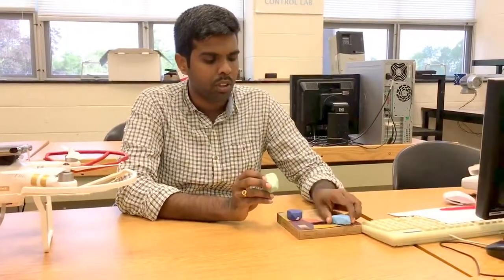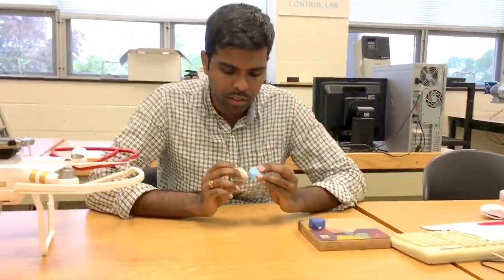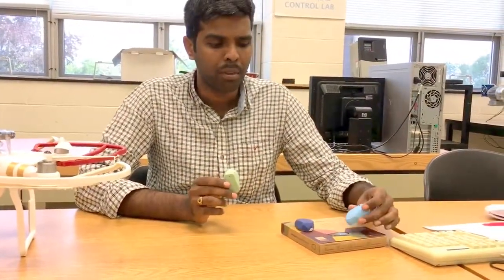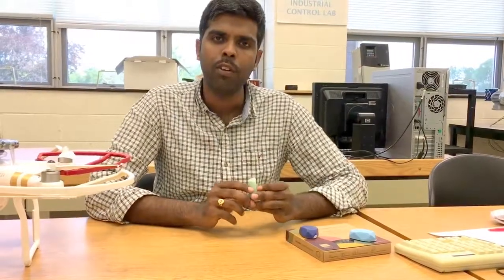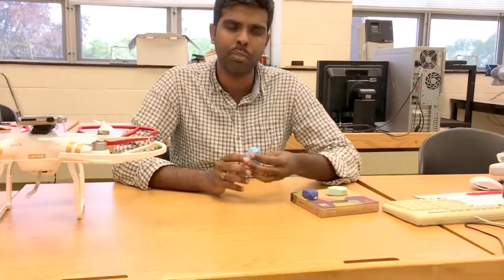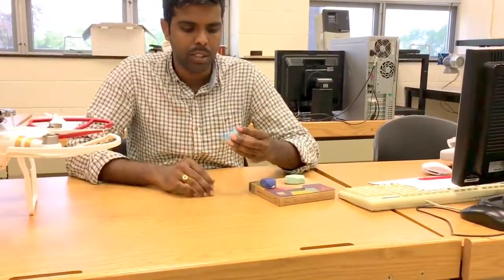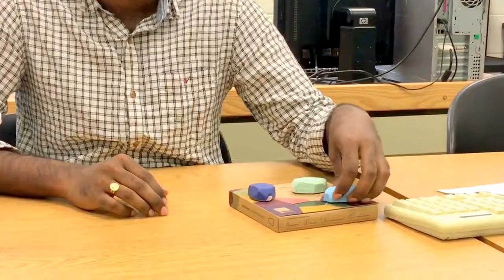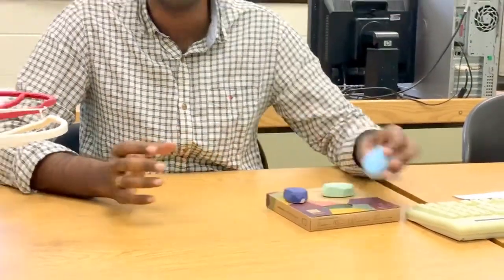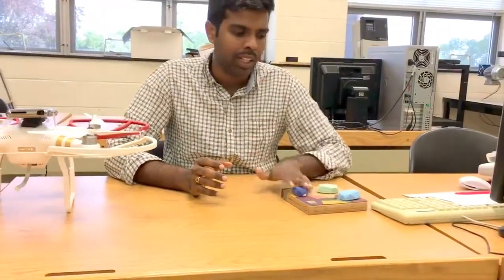These are the small stone-like things called beacons. A good example of a beacon is a lighthouse, which emits light to the ships continuously, 24/7. In the same way, these beacons give out Bluetooth signals continuously, 24/7, with a battery life of 5 to 6 years. Each Bluetooth beacon has a unique ID, which it continuously emits, and these unique IDs are picked up by any applications that we develop.